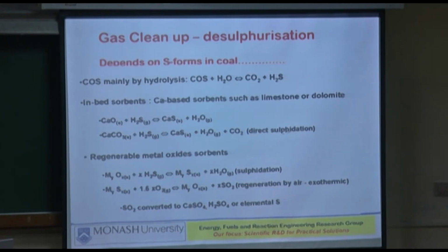And the second thing is you'll find a lot of literature suggesting, and Ben Anthony, as we were discussing, was the master of it, that the calcium oxide gets coated with other things, and then it cannot react with the incoming hydrogen sulfide anymore. So that's the problem. And if that happens, you cannot regenerate the calcium oxide. Very, very difficult. Then you will be looking at spending more energy to do it, which is not worth it.